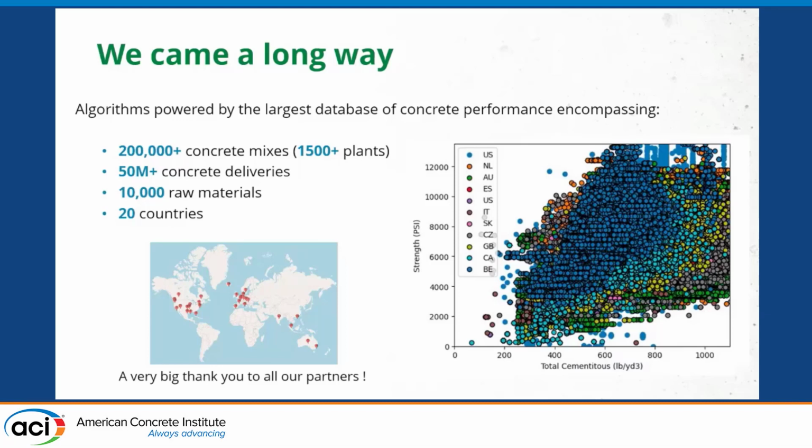is distributed. And once again, you can see that if you want to achieve a certain strength, this one's in imperial. So if you want to achieve 6,000, for example, there's a wide range of mix designs you can have to achieve this. This is only one. Obviously, I'm just looking at strength, but we're looking at a lot of other things, and it gets more complicated and complicated. So what are we actually wanting to do with this?